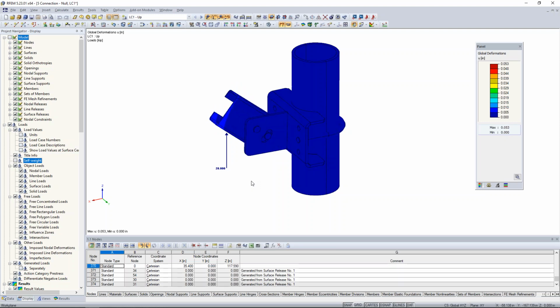In the event we need to reactivate that solid again, all we need to do is change the material solid back to a material element instead of null, and then maybe modify these loads slightly, and then you can rerun it with the double section shown. So that's a great example of how we can use that null solid option. All right, so that obviously makes up a bulk majority of our example today.